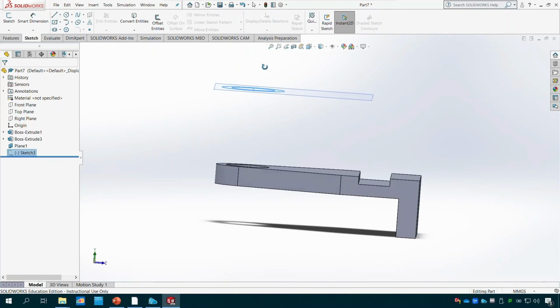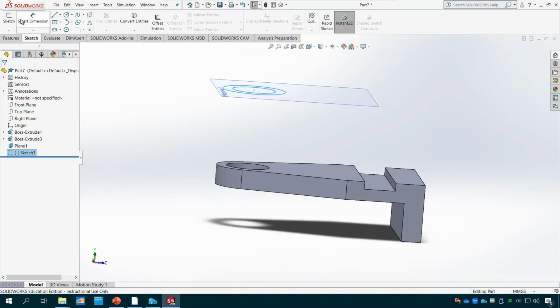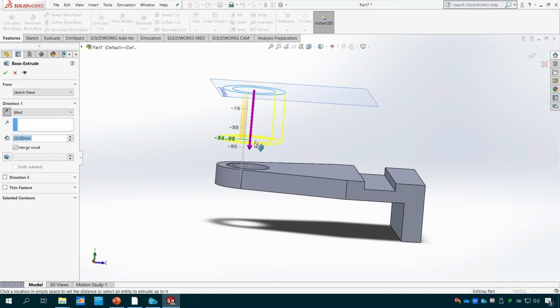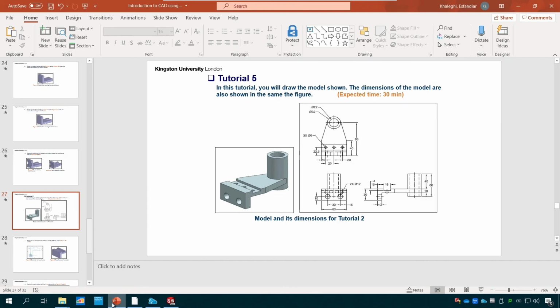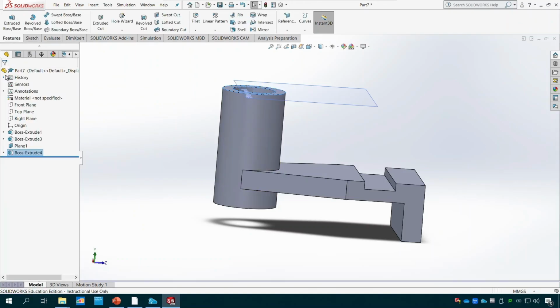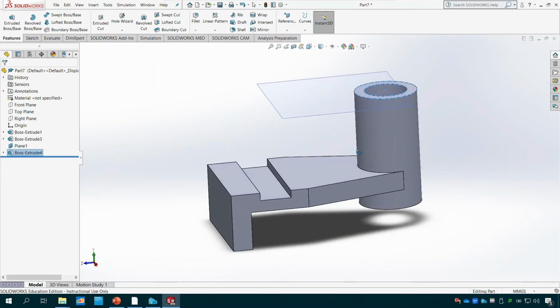So what I'm trying to do now, I'm gonna click on extrude, and then make an extrude of basically what we have there. We're gonna make an extrude of this 60 in here. And something is really important, make sure you merge the results at the end, because otherwise, the same as what we discussed, we don't get one single body. So join them together, and you can see that this is what we got on there.